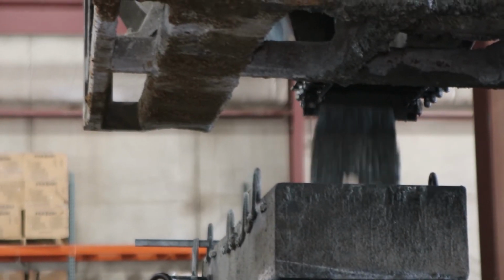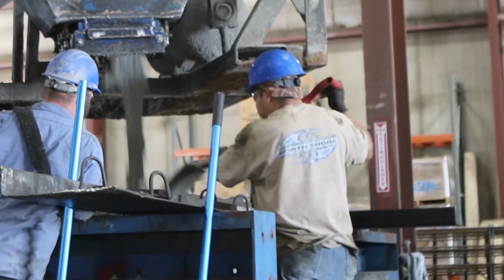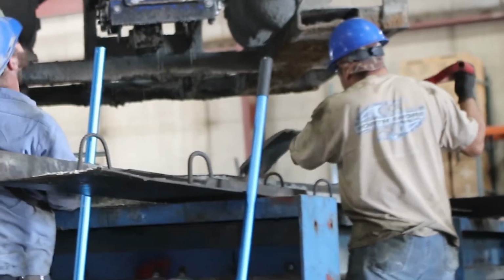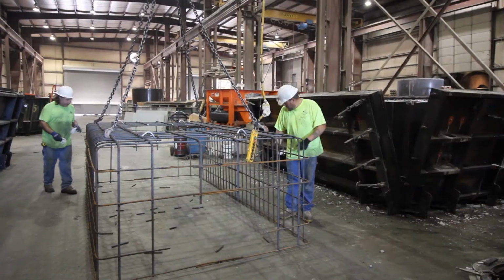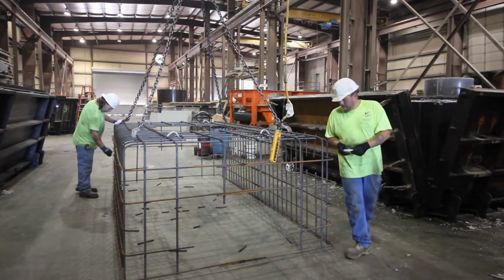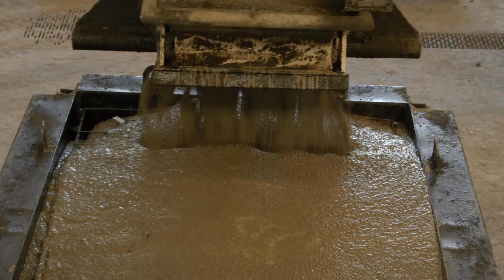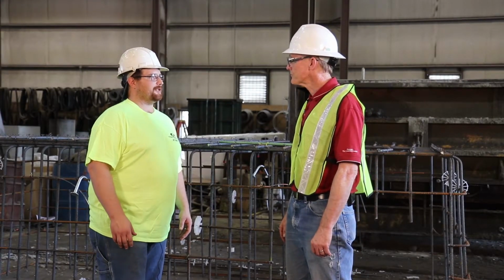You also need to ensure your cage is rigid enough to stay in shape during the concrete casting operations. It's important that the production supervisor or pouring crew observes the steel reinforcement to ensure there is no movement of the steel that could place it out of tolerance. Movement indicates additional spacers or chairs, wire ties or tack welding are needed to keep the steel in place. The worst time to find out that your cage was not built right is when the concrete hardens and the form is removed. So finding issues early will not only save your product, but save you from unnecessary hardships in the future. Now it's time for QC to do the final inspection before pouring.